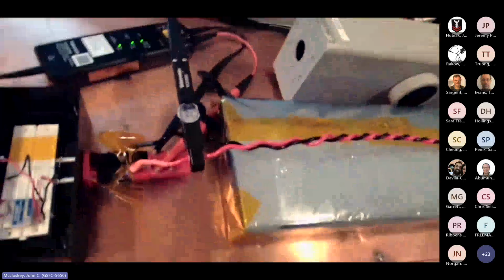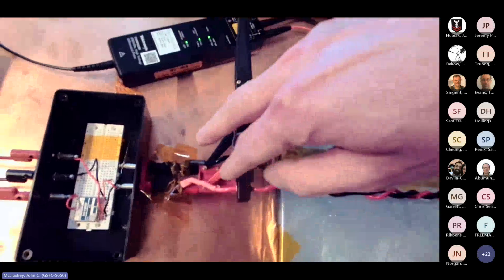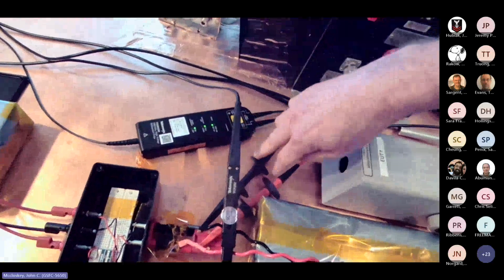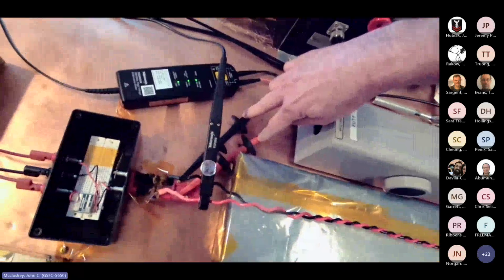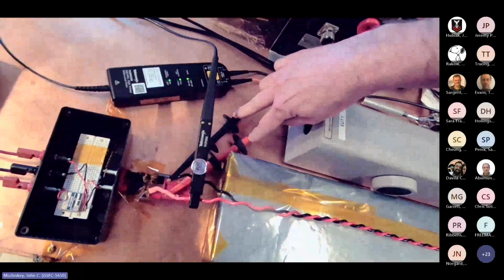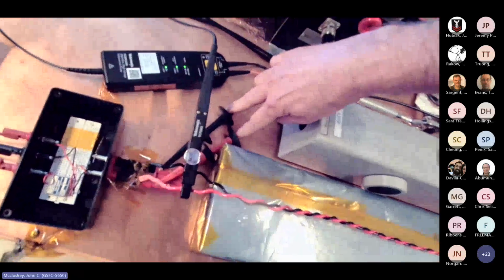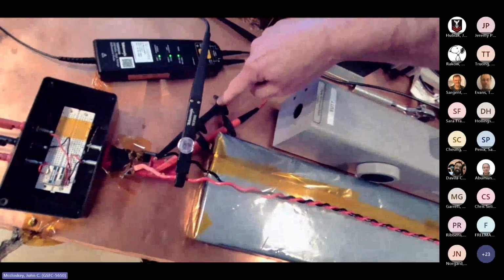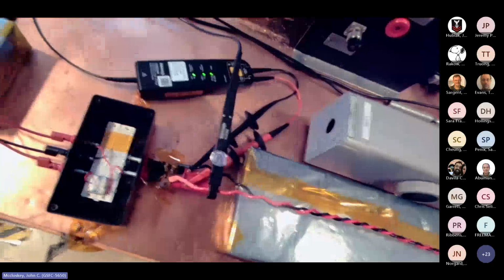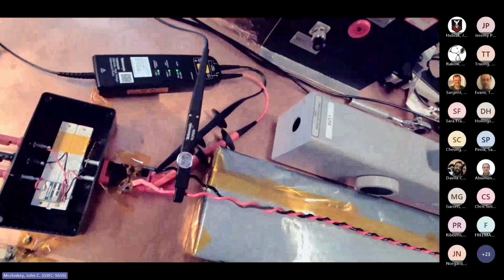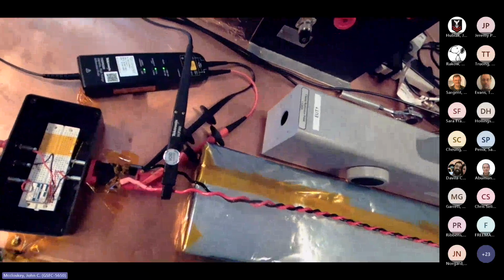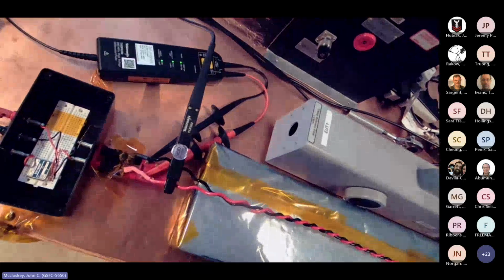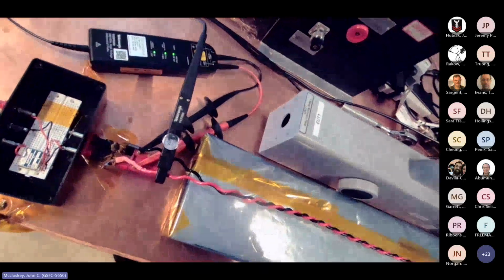So what we're looking at is the input voltage. That's with this high impedance differential probe here. I like to use differential probes whenever I can. Because with single-ended probes, the reference is actually tied to the case of the scope, which is tied to facility ground. And that can cause some strange things in your measured results if you're not careful.